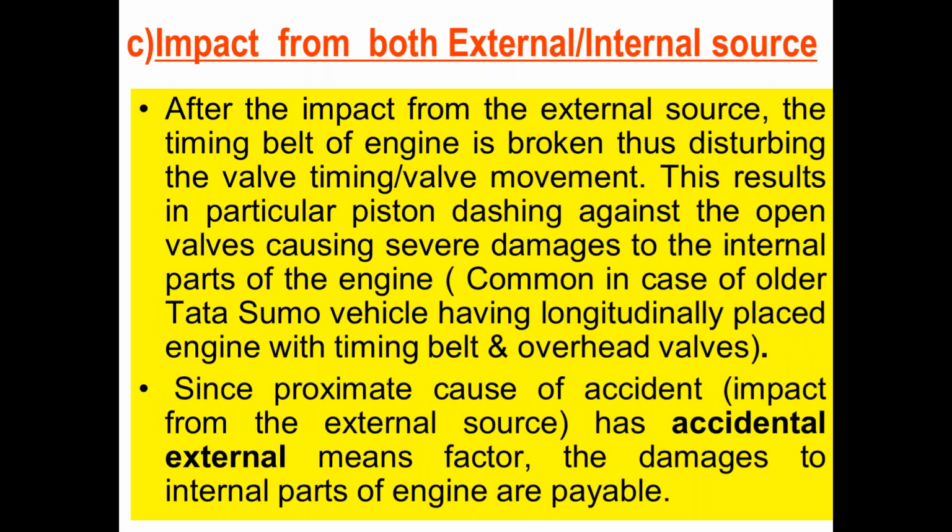Impact from both external and internal source. After the impact from the external source, the timing belt of the engine is broken, thus disturbing the valve timing and valve movement. This results in a particular piston dashing against the open valves, causing severe damages to the internal parts of the engine.